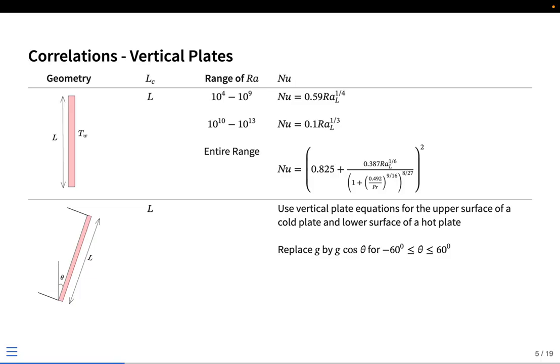So for example, when we discussed natural convective flow, or previously forced convection, even though it can be of different geometry, we eventually came up with something called a hydraulic diameter, which gives us the equivalent geometry dimension, and we have used it to define our Reynolds number, and our Nusselt number is related to that Reynolds number and Prandtl number. In a similar way, a natural convection process is governed by the Rayleigh number and the Prandtl number. These are the two parameters that will govern.